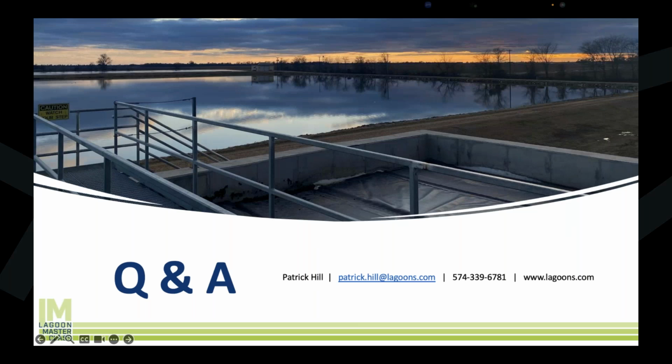When we are doing an LC50 test on our lagoons, the fish keep dying from the ammonia toxicity. How can a northern cold climate aerated lagoon system deal with this? Well, the issue is that the nitrifiers that will break down the ammonia that's causing the fish to die don't like to grow in cold weather.